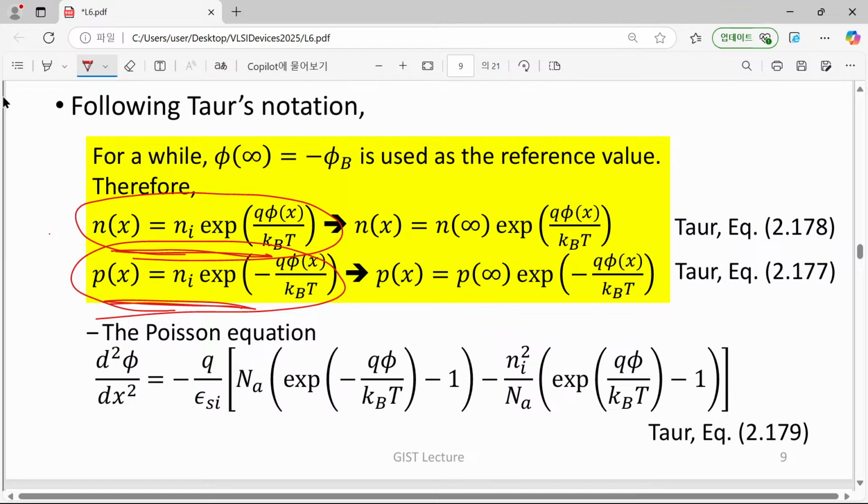Yes, but here we have to be a little bit careful. As I told you before, the surface potential is not the potential itself, but is referenced to the one far away from the surface, so the substrate potential becomes the reference of the surface potential.